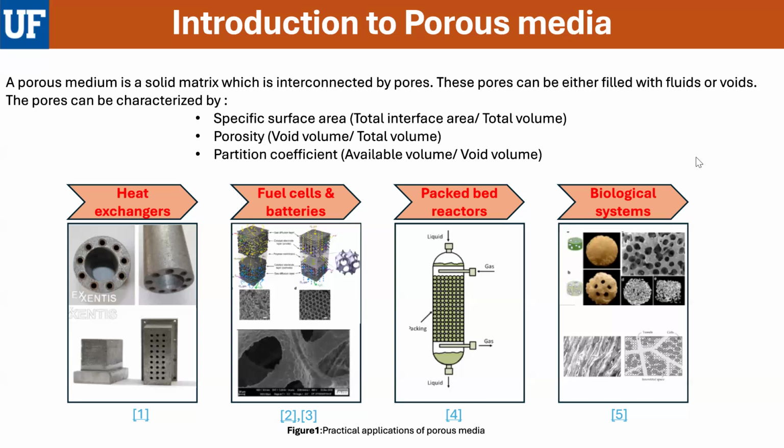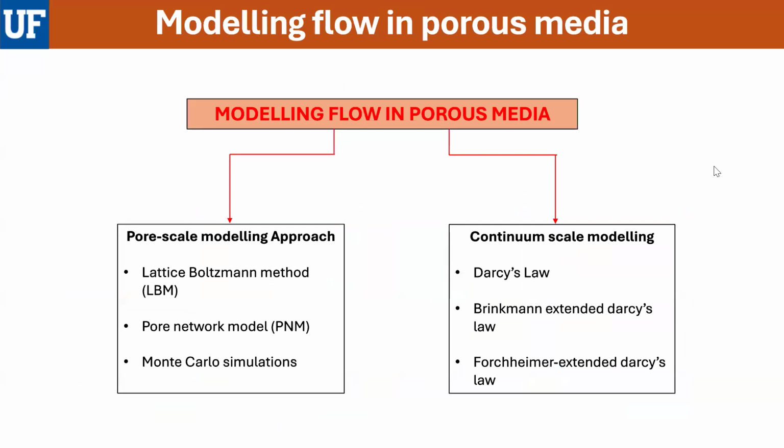In order to do that, there are basically two approaches. One such approach is the pore-scale modeling approach, and the other is the continuum scale modeling approach. In the pore-scale modeling approach, we are focusing only on the individual pores rather than the whole porous media, and this is done at the microscopic level, from 1 micrometer to 10 nanometers. In the continuum scale modeling approach, the porous medium is considered as a continuous media where the pore properties such as porosity, fluid velocity, and permeability are averaged by taking a representative elementary volume.